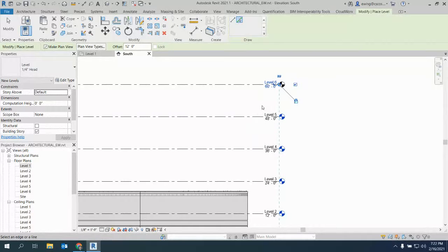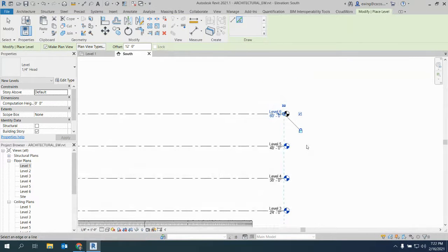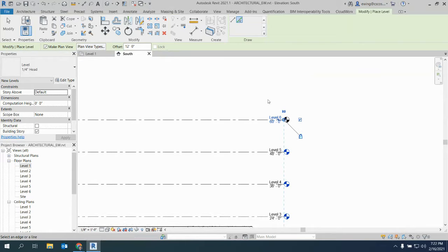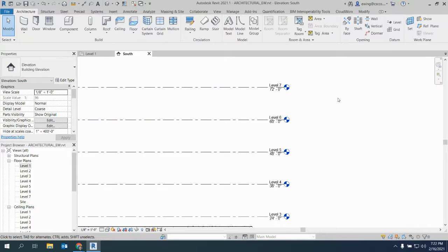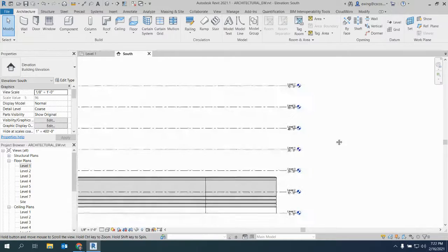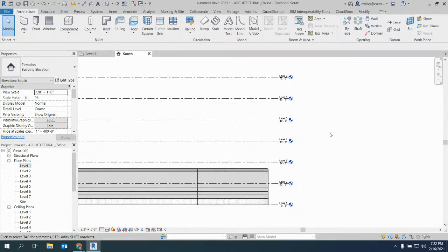Now notice how slow I'm going. Now in Revit, I found that you just need to be more deliberate with what you're doing. Again, you kind of slow it down, and trust me, you can probably already tell I'm a pretty hyperactive person. So it took me a while to get used to this process, right? So we're going to hover over level 6, and now we have level 7, and I want you to hit escape a few times. Now hopefully everyone got that.